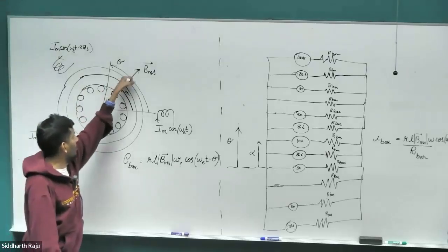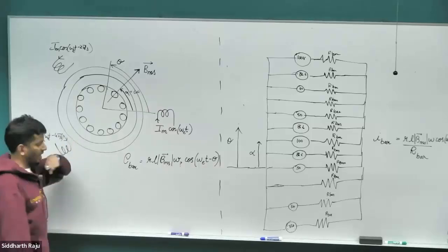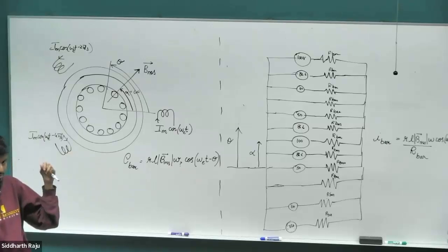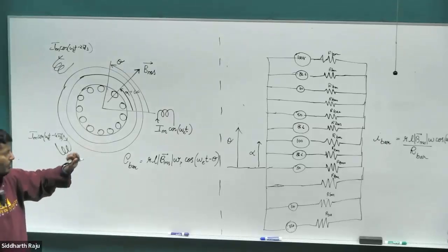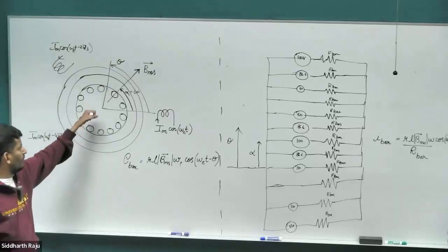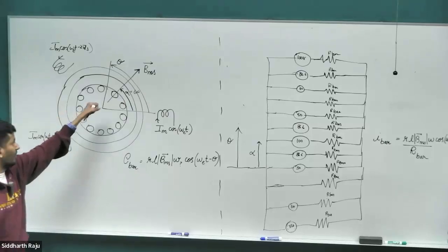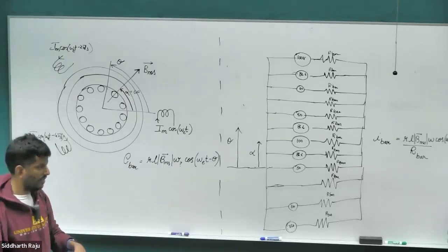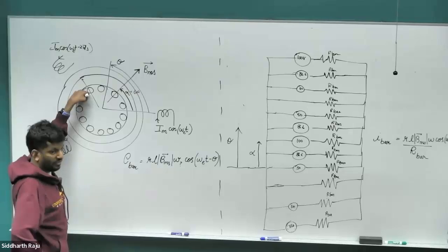Right? For this given orientation, let's say this alpha is 60 degrees, which of these bars would have the highest EMF across it? You don't need to look at the formula, you don't need to remember the derivation, try to get an intuitive feel. The reason we introduce the math of space vectors is to move beyond having to do the math, right? To give an intuitive feel. So if the magnetic field is along this direction, the maximum of the magnetic field, which of these conductors would have the maximum EMF across it? 90 degrees. 90 degrees. Right? This one from here? Yeah.